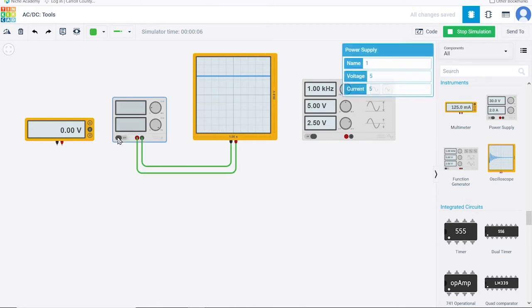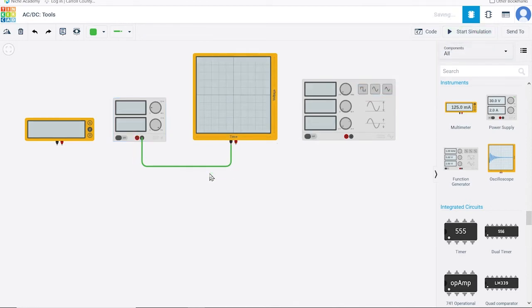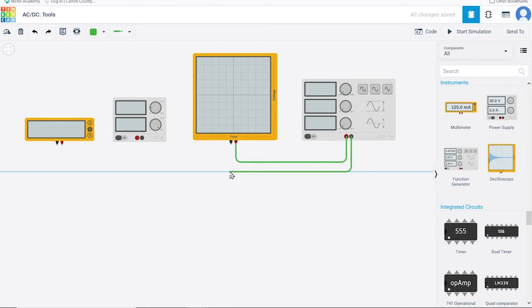We'll use one here to demonstrate the difference between alternating current and direct current, AC or DC, as well as look at some signals in the DC range that are also time-varying or changing over time. Finally, we have the humble multimeter. In a vast majority of cases, a power supply and multimeter are all that are required to work with electronics in Arduino-based projects. The multimeter, as its name implies, is a multifunction sensor that can read voltage, current, or resistance based on the way it's connected to the circuit.